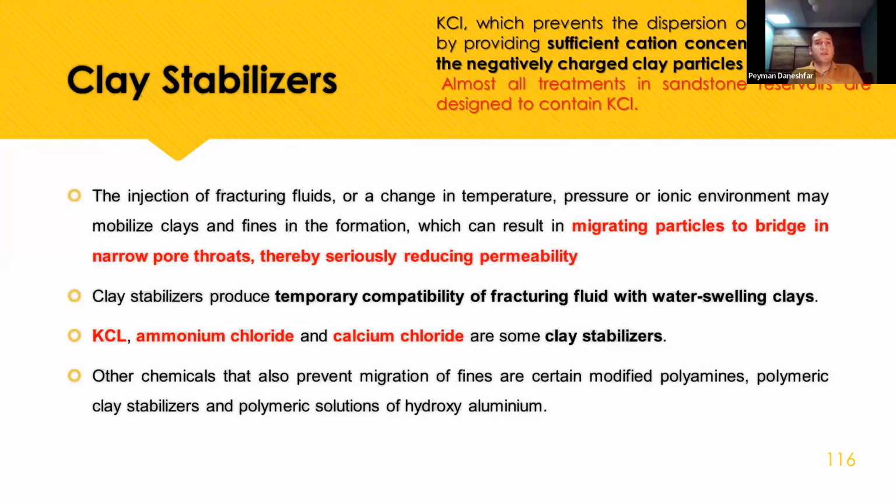Clay stabilizers are an important additive in hydraulic fracturing with water-based fluid, because when clay reacts with water, its volume becomes bigger and it will plug the pore throats, and this is not good for the formation permeability and other things. So we use clay stabilizers in our water-based fluid such as KCl, ammonium chloride, and calcium chloride.